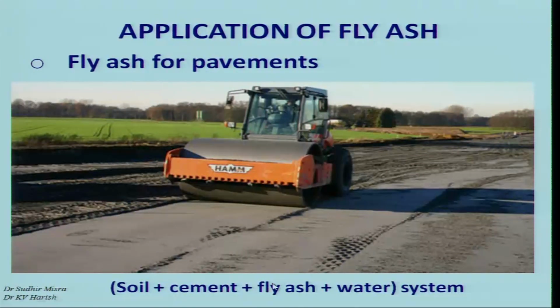And remember that in these types of systems, the effect of water cement ratio on compressive strength is very different from that of the Portland cement based systems. In this case, the water cement ratio is not a huge factor. Of course, the water content is a huge factor, but the strength of the system is primarily from the amount of compaction that is achieved by using the rollers or compactors. So, this system is primarily based on the density-strength relationship, which goes along the principles that are used in soil. So, this is again a totally different system.